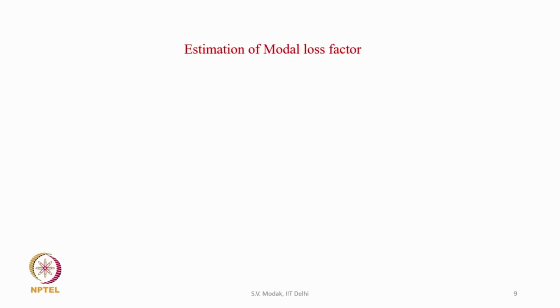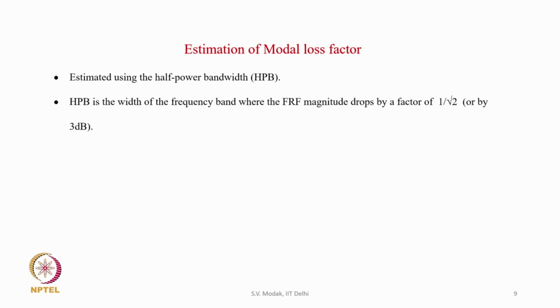Now, how is the modal loss factor estimated in this method? This is estimated using the concept of half power bandwidth. What is half power bandwidth? Half power bandwidth is the width of the frequency band where the FRF magnitude drops by a factor of 1 by root 2.